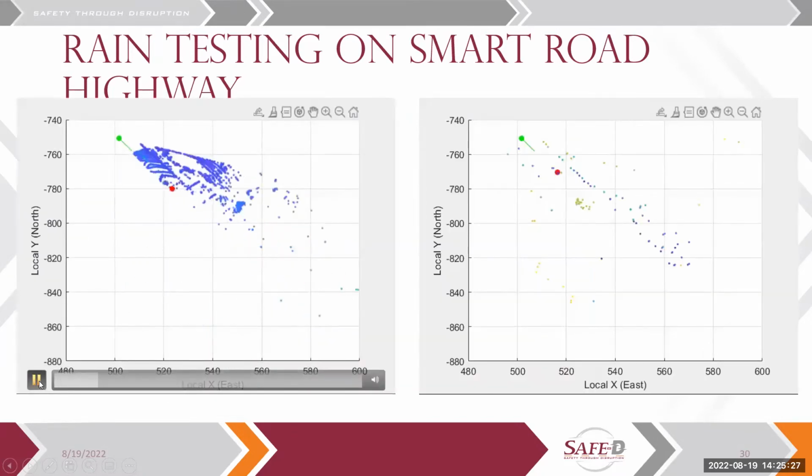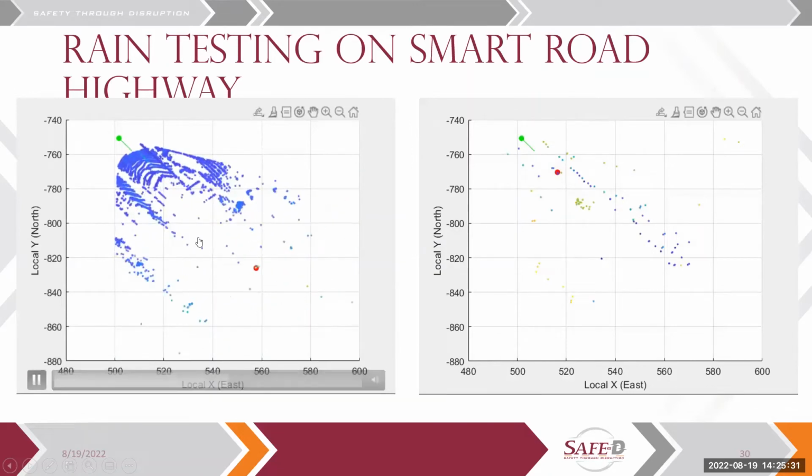Here you can see we get a little bit more range to the information, and as we're traveling through the rain cloud, you can see the sensor starts having this error. These 2 points here are basically the tail lights that it's picking up. So once we go deeper and deeper into the rain, the distance estimate is getting worse.